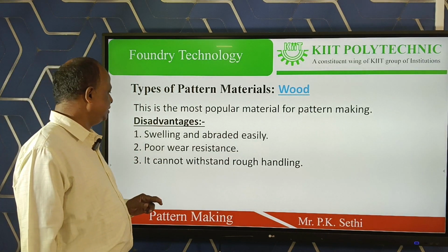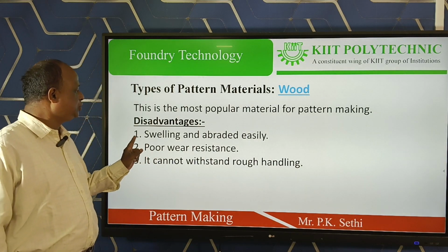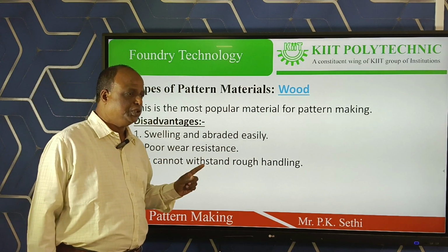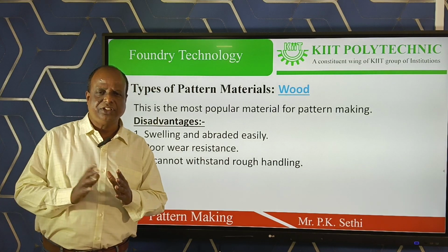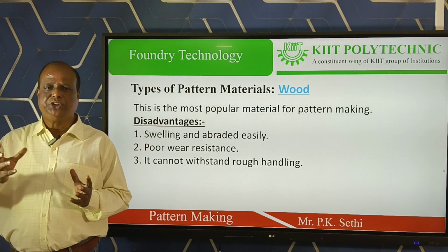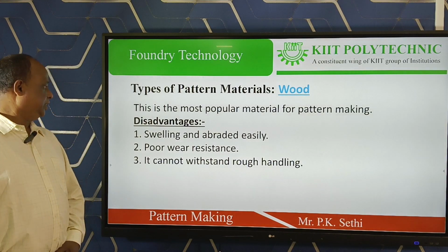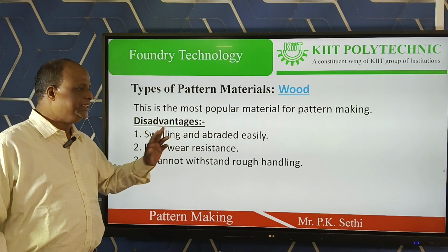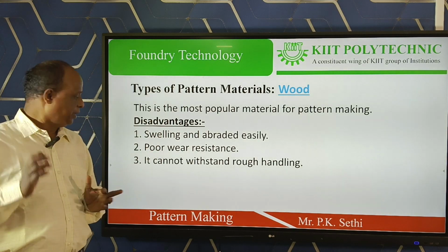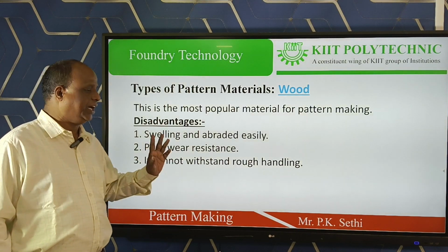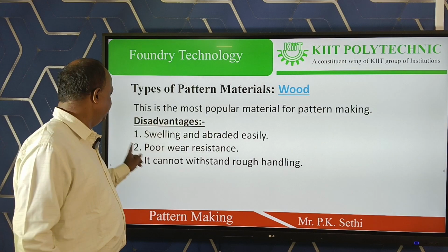Next, what are the limitations? It can swell easily and abrade easily. Swelling means it becomes larger in size due to absorbing moisture from the atmosphere. Second is poor wear resistance, as it is easily scratched. And third, it cannot withstand rough handling, and it breaks easily.